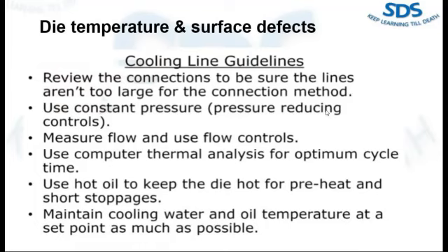At least you can measure manually if you don't have a flow meter or are not able to purchase one. You can easily measure the flow of your water. Put a 20-liter bucket, start your stopwatch, and count how much time it takes to fill the 20-liter bucket in inflow, and in the same way you can measure outflow. So manually it can be done.